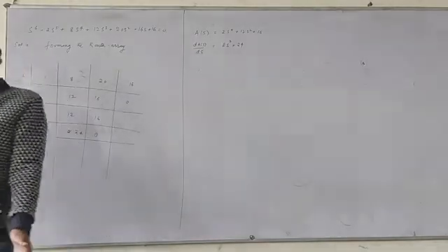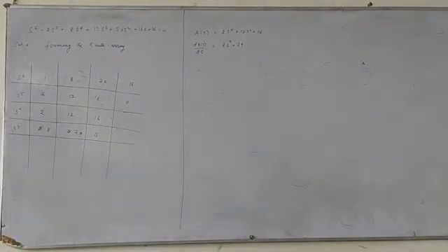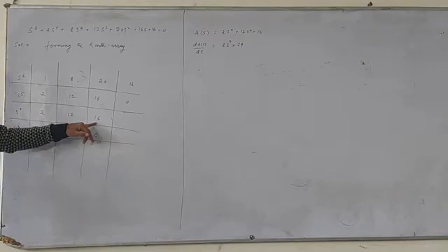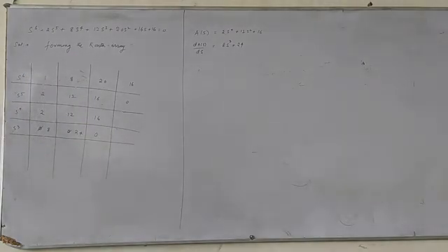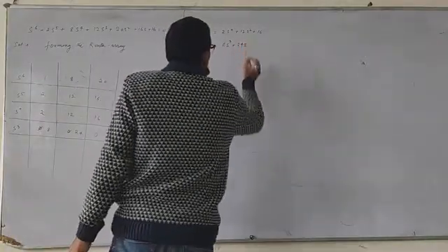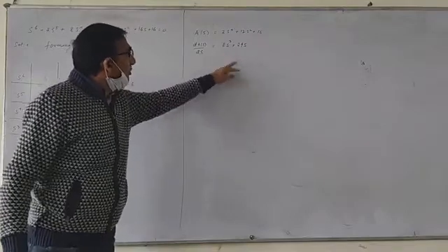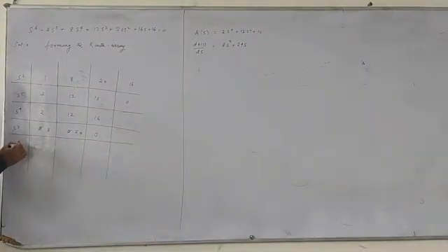When the row of 0 appears prematurely, we have to take the auxiliary equation. This should be s^4, this should be s^2, and this should be s^0. We have taken that and differentiated it with respect to the independent variable s. We get 4 into 2 is 8, 8s^3, 12 into 2 is 24, 24s, and the constant is 0. So replace these coefficients here. Now again, continue to form the Routh array in the similar manner. So 12 into 8 is 96.